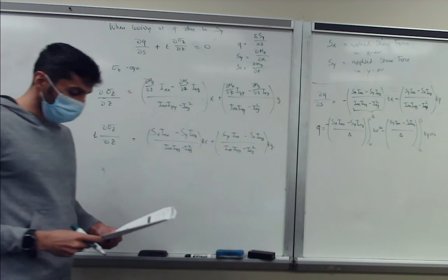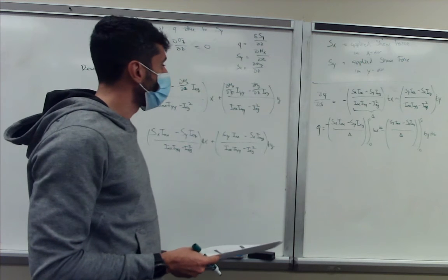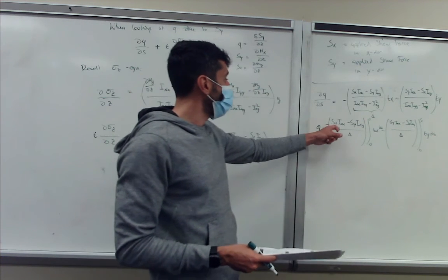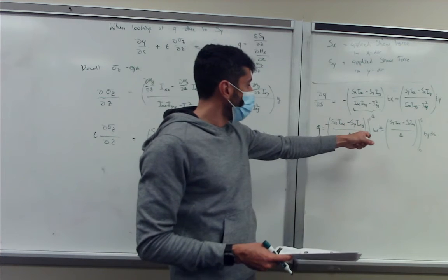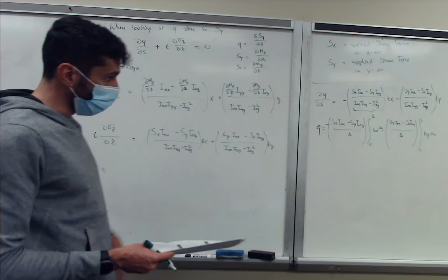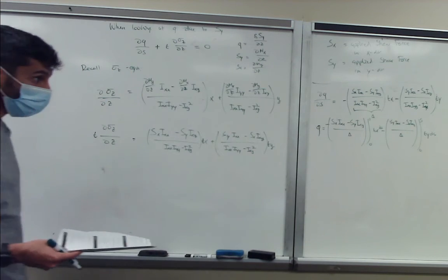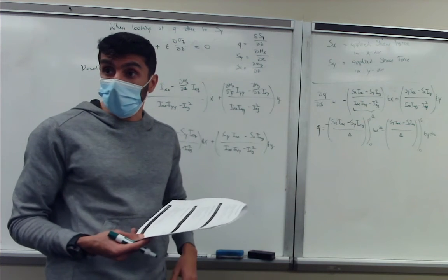So this is our final equation of shear flow. We can spot that our shear flow is a function of our applied shear forces. Those are given applied loads, and they do not vary with s, which is the length path around the cross section.